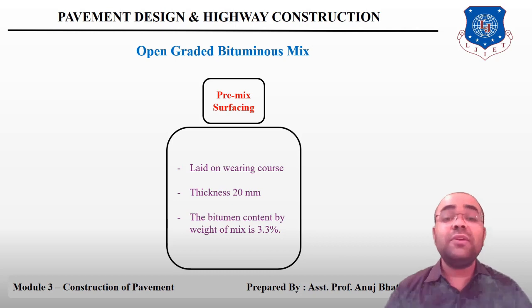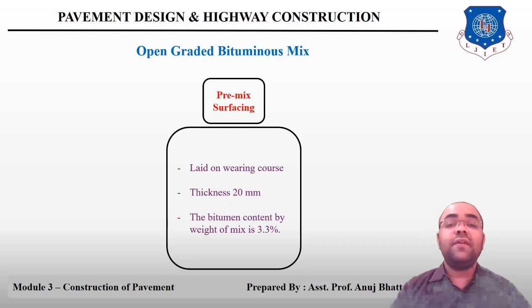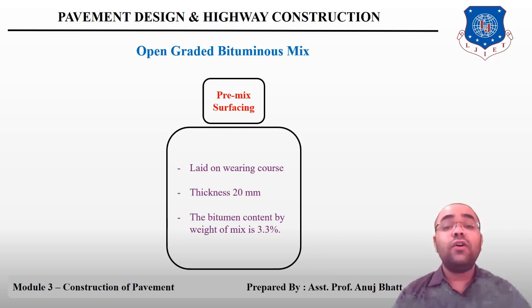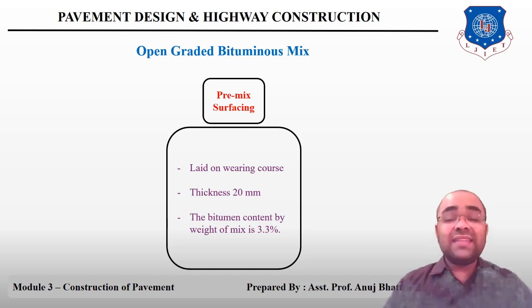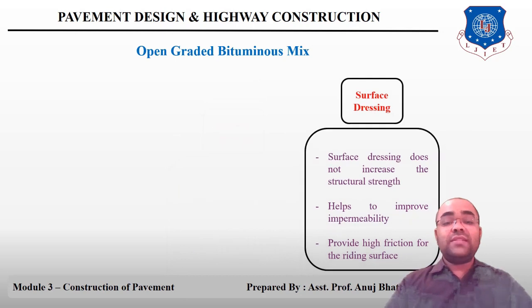The mix shall be transported from the mixer to the point of use in a suitable vehicle or hand barrows. We can say in this particular mixture, the bituminous content by weight of mix is 3.3%. The next open graded bituminous mix is surface dressing.